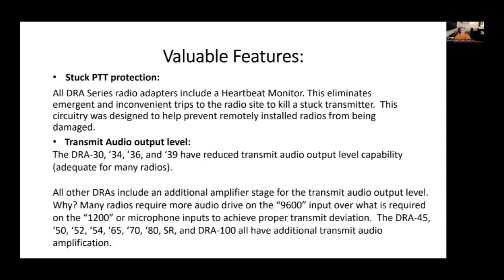Some of the other things that the DRAs do, and this is really important for deployments that are at repeater sites or remote locations where they're going to be unmanned: we have a stuck push-to-talk protection. This includes a heartbeat monitor, and it eliminates inconvenient trips to a radio site to kill a stuck transmitter.